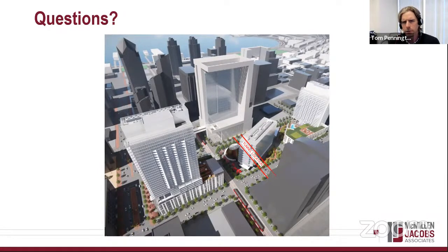And like I said earlier, the SEM method can be adapted. And in this project, it sort of had to be when we encountered this unknown and undocumented well structure beneath the existing courthouse basement. If we had hit that with a tunnel boring machine, depending on its composition, we might not have been able to get through it, or at least might have had to spend a lot of time trying to remove that obstruction before we could continue excavation.